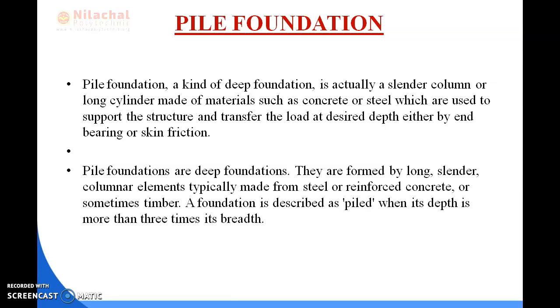Okay, and in these cases the foundation of the structure has to be taken deep, with the purpose of attaining a bearing stratum which is suitable and which ensures stability and durability of the structure. And the bearing stratum is not the only case. There may be many other cases. For example, the foundation for a bridge pier must be placed below the scour depth, although a suitable bearing stratum may exist at a higher level.